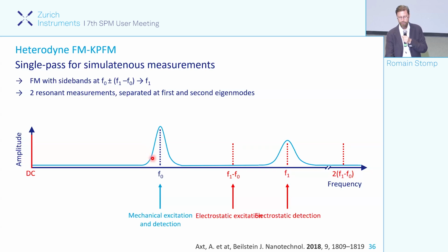But that's very crowded. So that means the bandwidth is limited. It's easier to have crosstalk sometimes, but also if you modulate faster, then you will quickly go out of the resonance, and therefore your signal is going to be attenuated. So it makes it very, very difficult in terms of SNR as well.